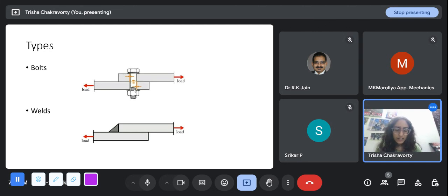Shrikar, I think you asked that if we can take a normal bolt and we can sufficiently tighten it, it will act as a friction type bolt, because in a friction type bolt, the basic force is not taken by the bolt material itself. Instead, it is tightly clamped, so that the two plates that we are connecting are clamped together, and the normal reaction transfer between the two plates is high, and so the friction developed, that is mu n, mu is the coefficient of static friction, is high enough to take the load. But in bearing and shearing type bolts, this friction is not taken into account, though there may be some friction. We don't take that into account, and we assume that the bolt material itself takes the load using shearing and bearing.